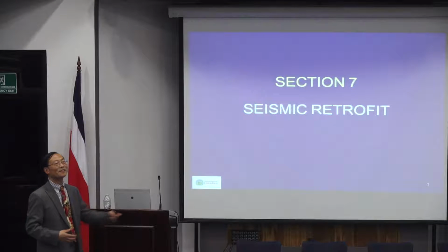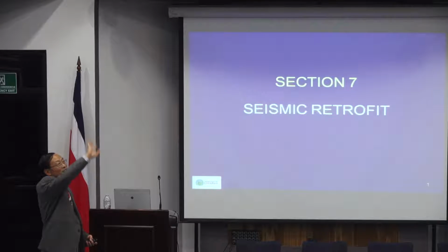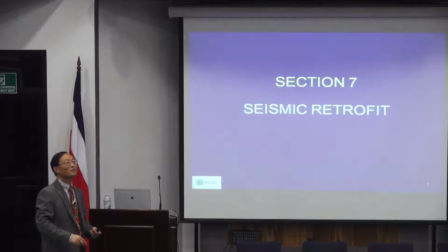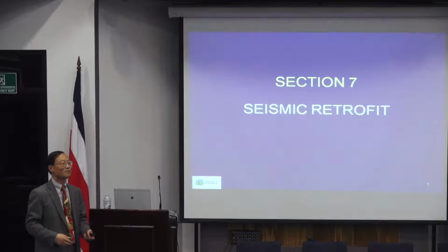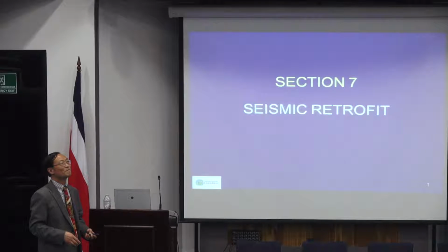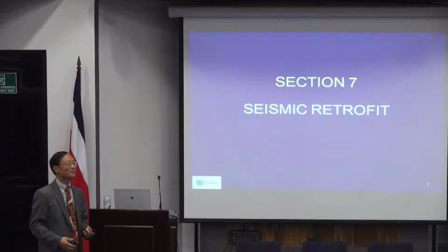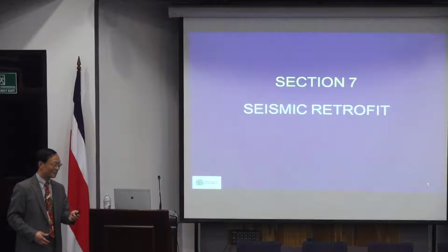If you don't need to enhance the capacity, if it is just a crack or spalling that you patch, we typically call it repair. In other words, if it does not change anything, we call it repair. And retrofit is something in between. Retrofit is when the bridge is okay if there is no earthquake, but if there is an earthquake, it may not be sufficient. So that's just for a particular reason.